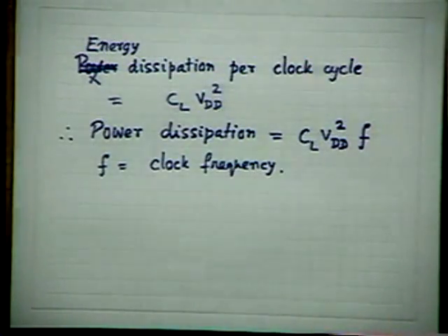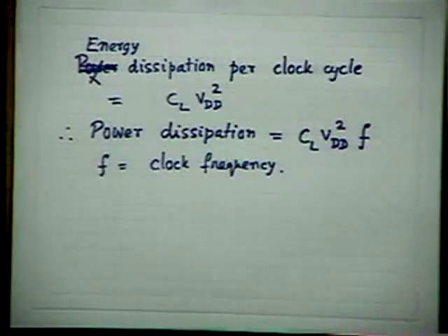That is why the present generation VLSI is gradually tending towards lower and lower supply voltage. Of course, it is now limited to around 3 volt and then 1 volt. And that is due to this power dissipation in CMOS. That is a primarily important thing. And it also has some other advantages. For example, the various high voltage induced effects in CMOS are got rid of. But the problem is of noise margins. It will be more susceptible to noise. But fortunately, you can design systems in such a way that noise is minimized.